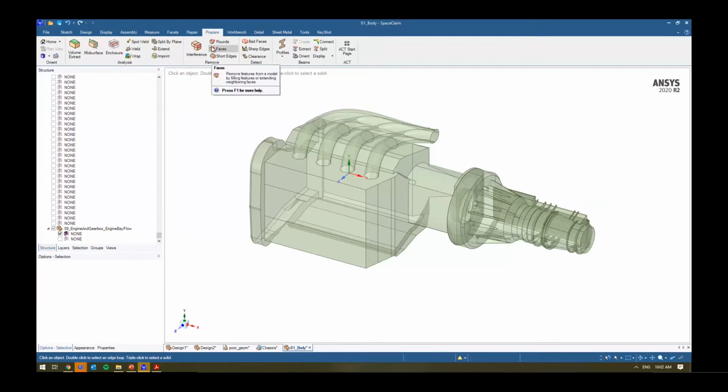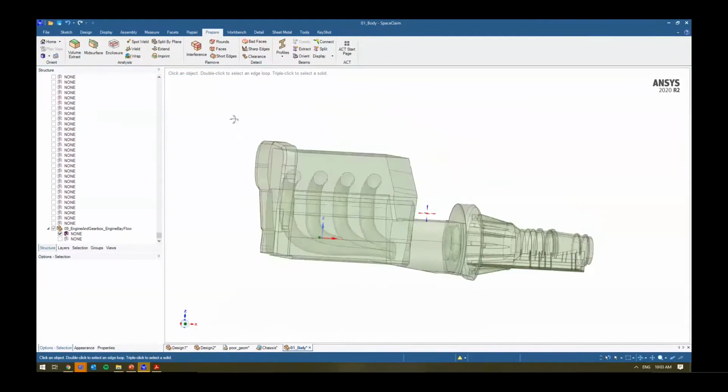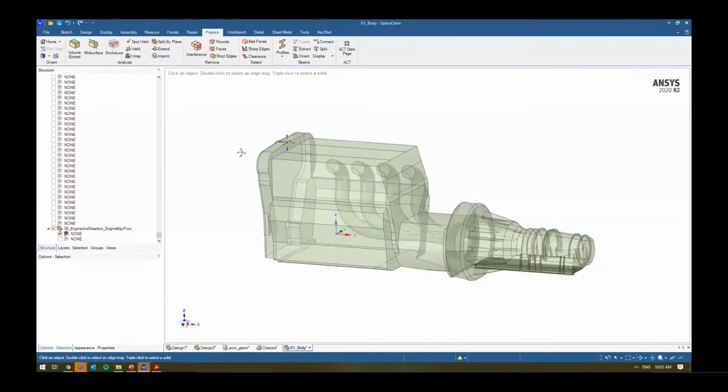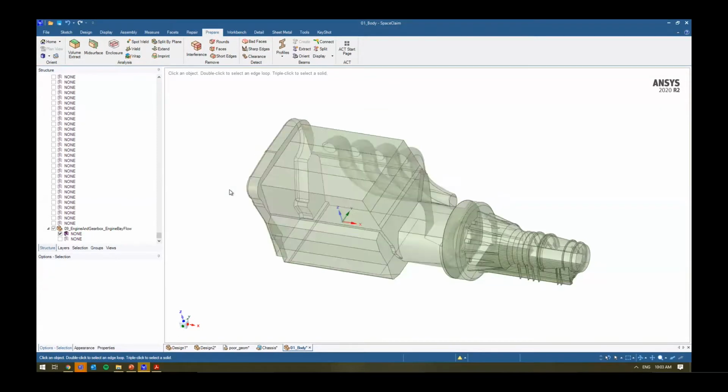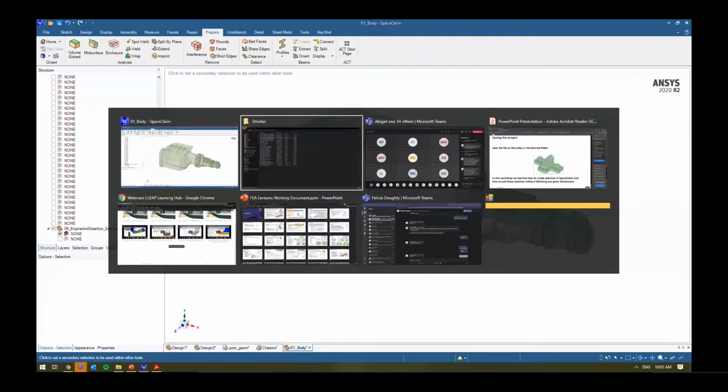Generally, what I recommend is if you've got some production CAD or something like that, with sketches that you need to go through and reference again and again, something like that might be living in SolidWorks. You've got a feature tree, and someone might want to, years from now, go back to that specific sketch and make some changes, right? That's where it might live for something like SolidWorks. But SpaceClaim, this is where I use as a pre-processing tool. So I pre-process the geometry, get all these things fixed such that I can bring it into Mechanical afterwards.